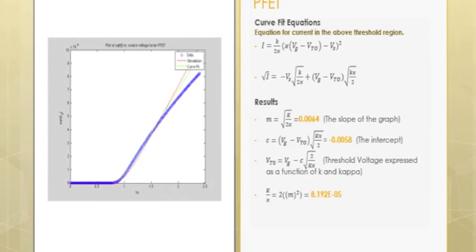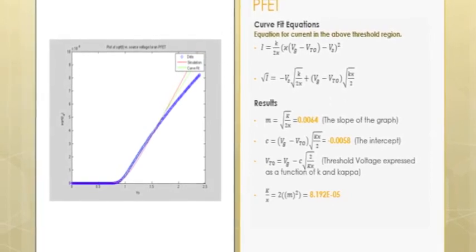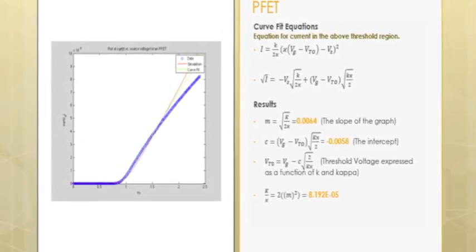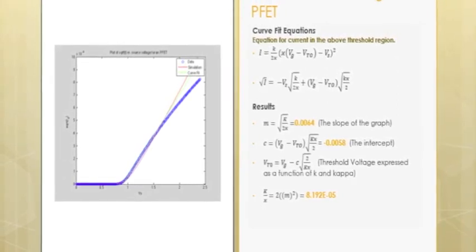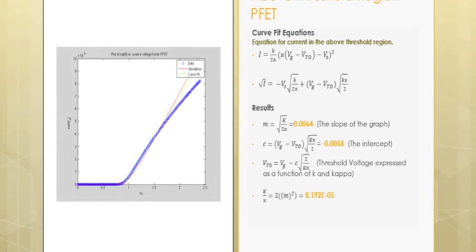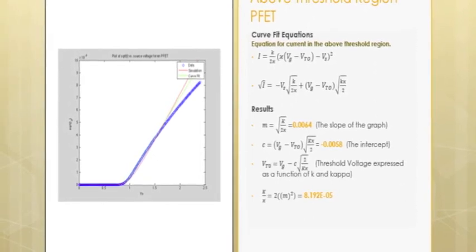This shows the above threshold voltage for the PFET. Using the equations for the PFET, we extract values for the threshold voltage in terms of K and kappa and an equation relating K and kappa, similar to the NFET.